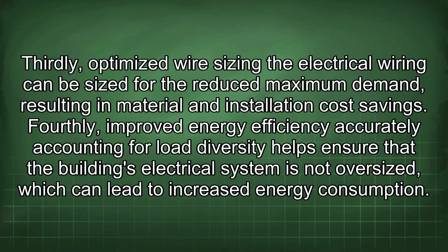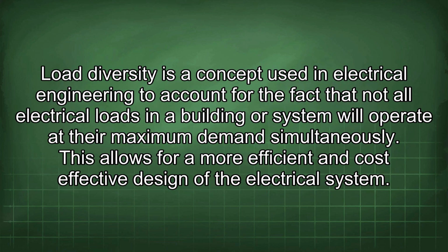Fourthly, improved energy efficiency. Accurately accounting for load diversity helps ensure that the building's electrical system is not oversized, which can lead to increased energy consumption. Load diversity is a concept used in electrical engineering to account for the fact that not all electrical loads in a building or system will operate at their maximum demand simultaneously. This allows for a more efficient and cost-effective design of the electrical system.